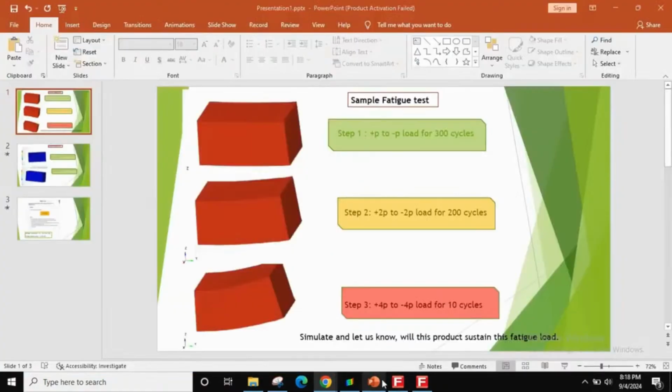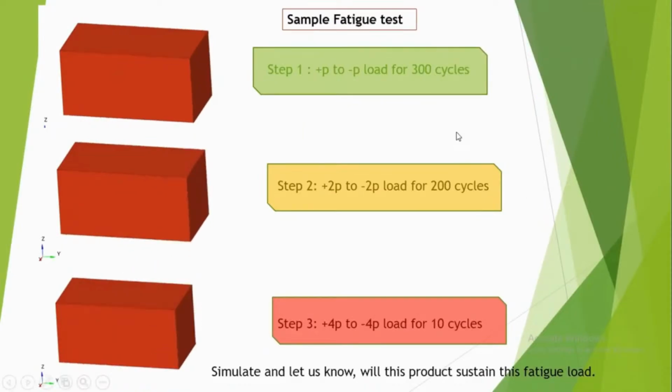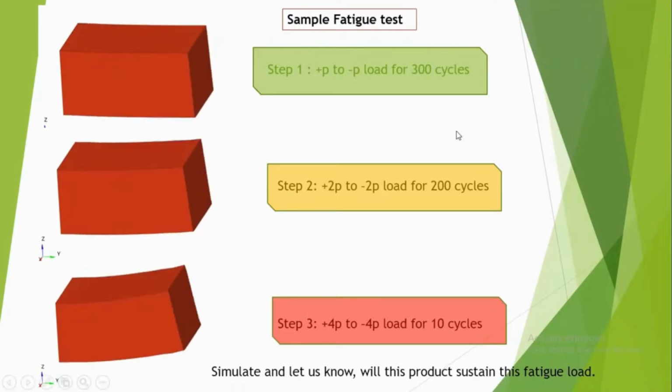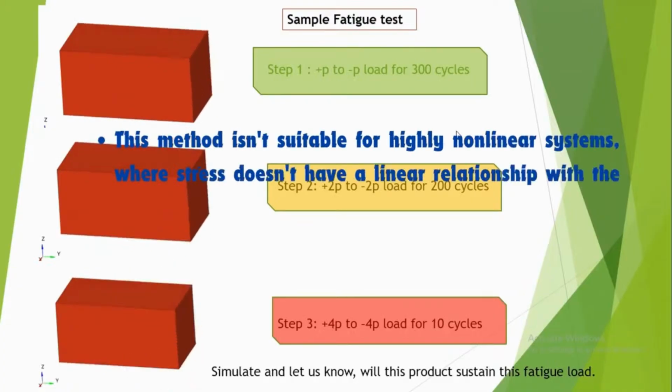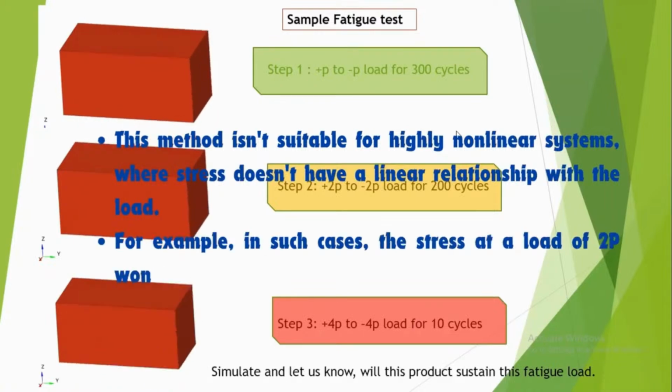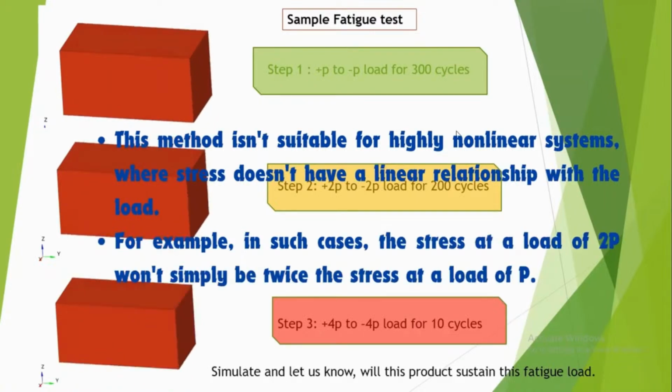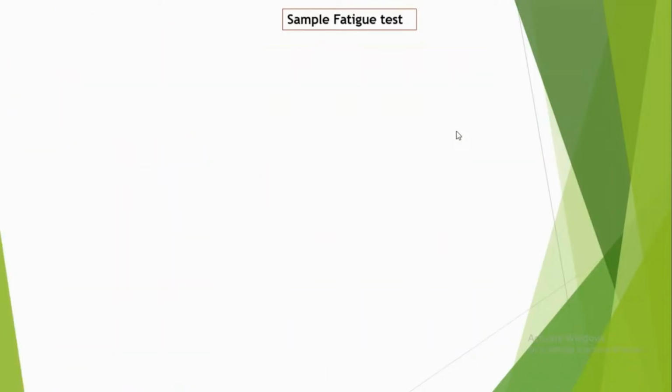But the problem comes if this is a highly nonlinear system. Then the scaling of the results from the Abaqus ODB, ANSYS RST or Altair OptiStruct S3D file might not be scalable, because this might be a highly nonlinear problem. Then what to do? Or suppose it is a linear problem itself, but the direction of loading is different,